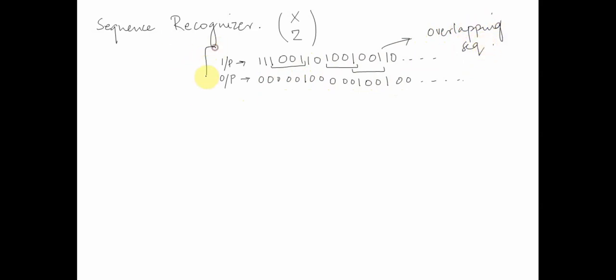So our intention is to build a circuit which, if it takes this as an input, produces this as an output. And if you see, this has to be done using a sequential circuit only, with a memory element, because the circuit should be able to store the previous states. If we are in a state where a 1 has come, the circuit should be able to remember that okay, 1 was encountered.